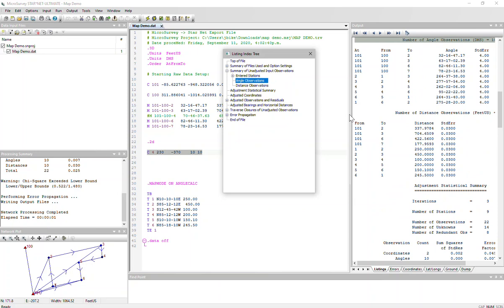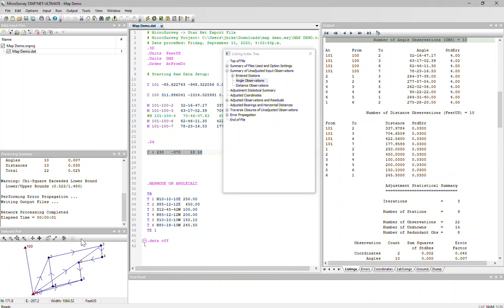And if I go in there, you'll see that it has, of course, computed the observations from the angles from the M lines that are up here, but it's also derived angles from all of these shots, and that it's getting that information from down here. And so it's just computed the angle, and it's computed the traverse using only the angles. So there you go.